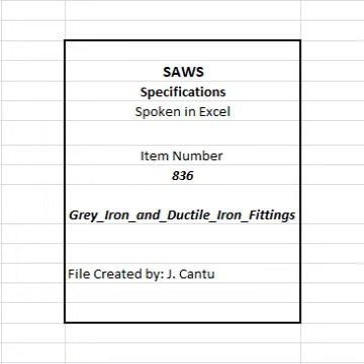836.3 Submittals. Contractor shall submit manufacturer's product data, instructions, recommendations, shop drawings, and necessary certifications. 1. For pipe 16 inches and greater, submit shop drawings signed and sealed by a professional engineer registered in the state of Texas showing the following. A. Manufacturer's pipe design calculations. B.